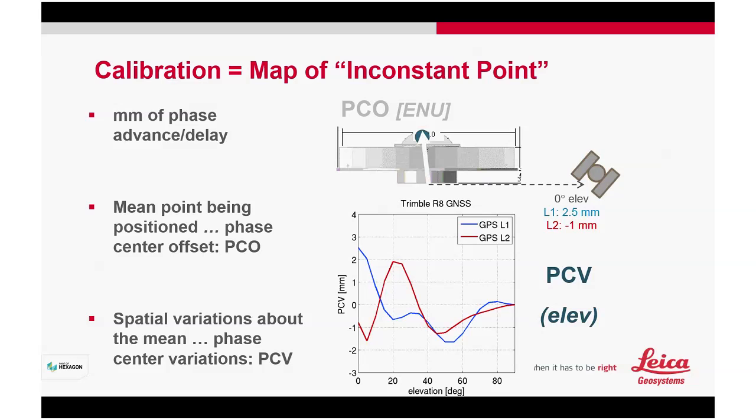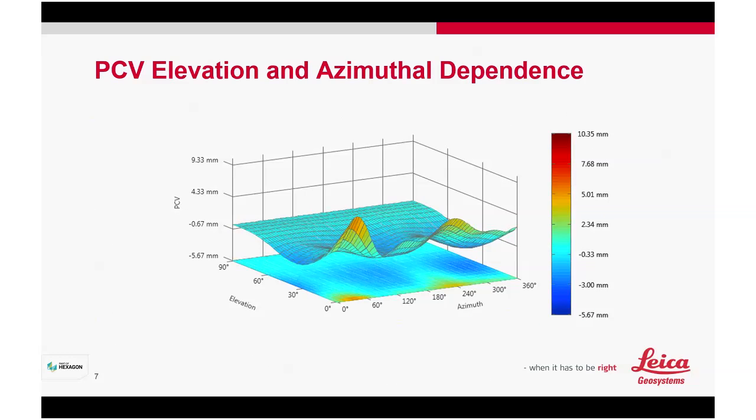Okay, there's an example. So let's say this satellite is at a low elevation, the phase center variation is like this, but when it goes up, the phase center in mm will be different. Okay, from -1 mm to +2 mm. Okay, and all this information will, as a result, affect your post-processing, the data, the accuracy. Okay, that's an example showing you not just elevation.